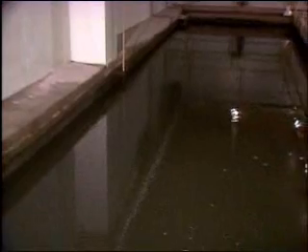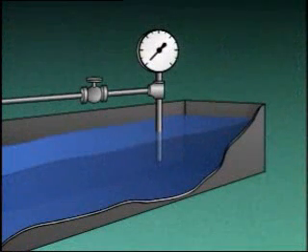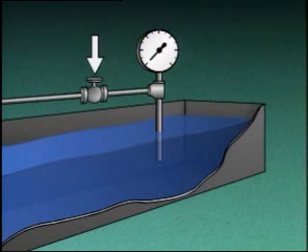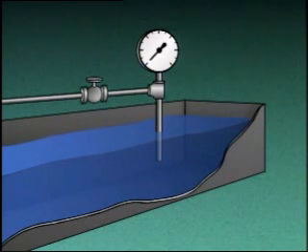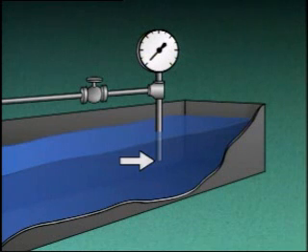An indirect liquid level measurement device called a bubbler system uses hydrostatic pressure in a slightly different way. It operates by forcing air out of a pipe that's immersed in liquid. The system consists of a pipe that's open at the bottom and connected at the top to a regulated air supply. There's also a pressure-sensitive gauge, which is used to indicate level. The opening at the bottom of the pipe is at the minimum level to be measured in the tank.